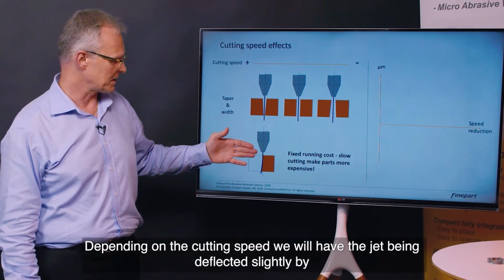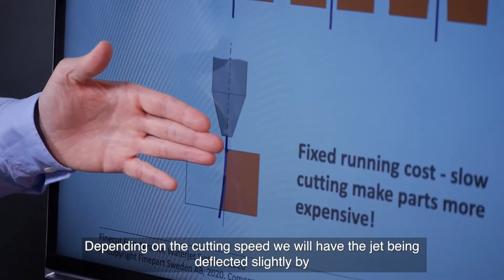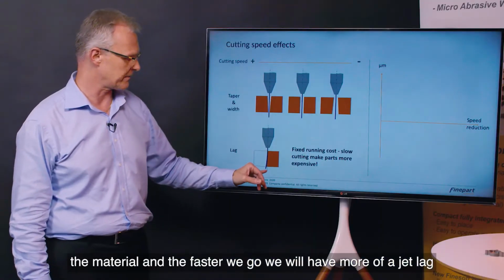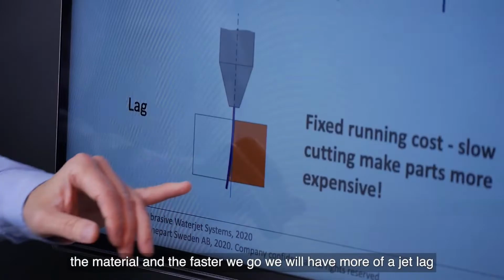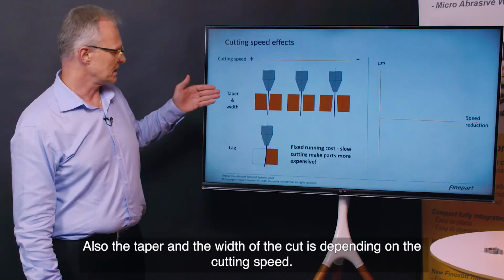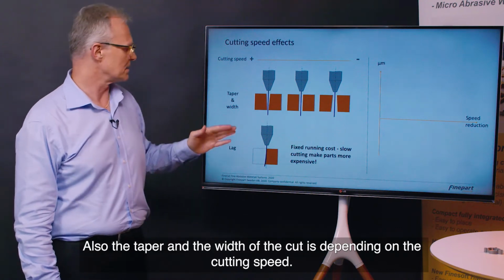Depending on the cutting speed, we will have the jet being deflected slightly by the materials. The faster we go, we will have more of a jet lag, with the bottom of the cut lagging behind the top of the cut. Also the taper and the width of the cut depend on the cutting speed.